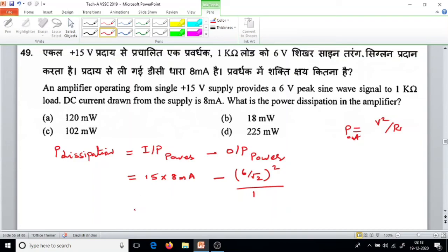When we have three variables, voltage, current, and resistance, we need not write milliamps and so on. I told in many videos how to use it, so please follow it. That is voltage in volts, current in milliamps, and resistance in kilo ohms. Keep it in the same format, then there is no need for unit conversions in your calculation.